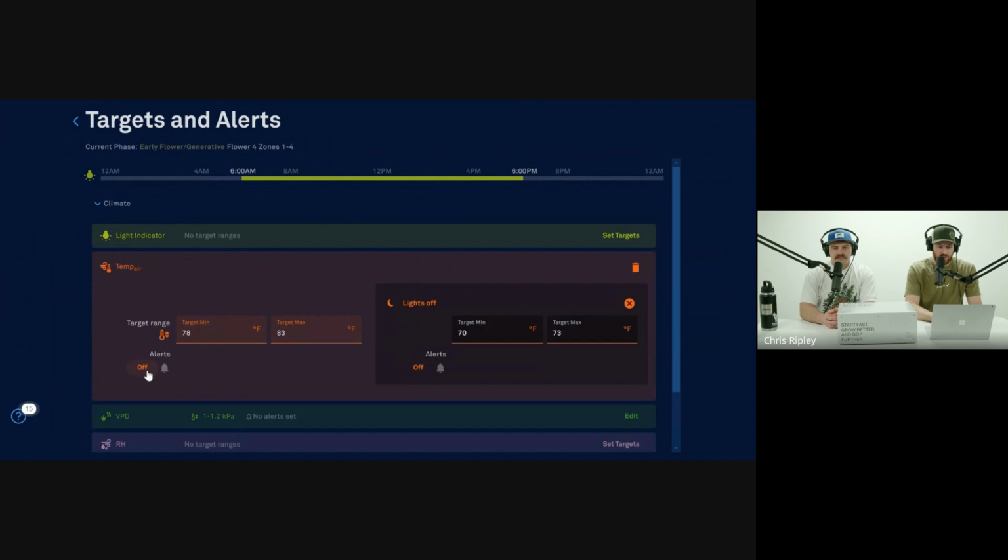And as always, we're welcome to set up alerts as well. Those alerts can be quite a bit tighter than they had been, specifically because now we've got that tight range that is accounting for nighttime, daytime differentials that you might be deploying. Yeah, it makes it easier to set an alert that you'll actually get if you're not achieving that overnight differential. If we're set historically between, let's say, 80 and 65, for instance, I'd want an alert if that room goes over 70 at night. And before we didn't have that capability. Now it's a lot more granular, easy to use.